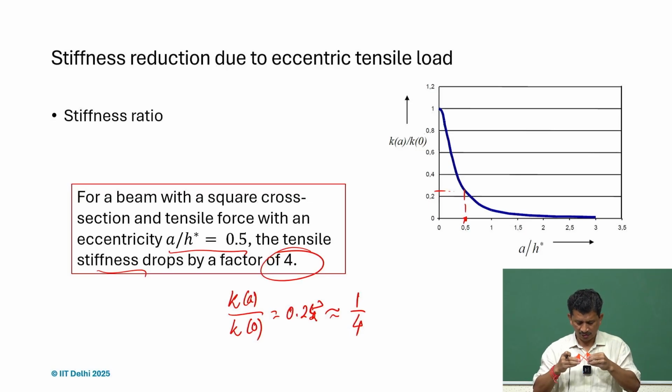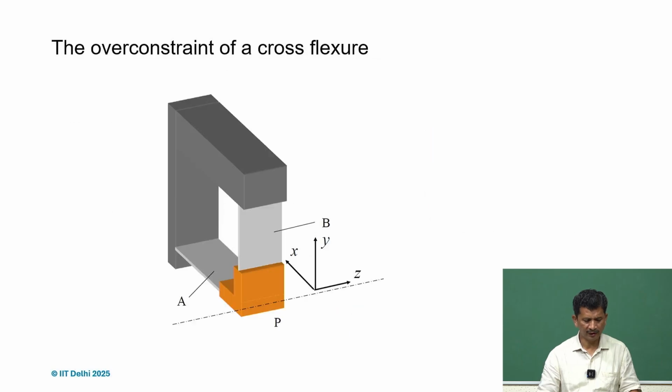Yes, we have a problem if it's a compressive load, since it's a slender part, so buckling will come into the picture, and as it deforms, the load capacity will get reduced. So it's very important to understand what kind of loading should be there and how it should be applied. So be aware of that.